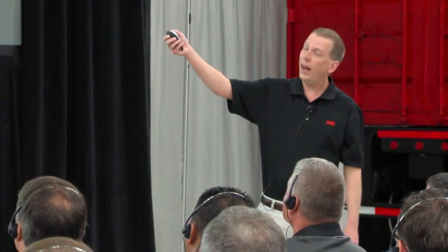Now, why is that important? Well, I said you could run half speed at half the voltage, right? And you'd say, well, that should be half speed. Well, we got this thing I talked about earlier called slip, which is a problem because the heavier the load, the more the slip. So I can think I'm running half speed, which would be maybe 900 RPM, and I'm really only running 850. Some applications wouldn't care.